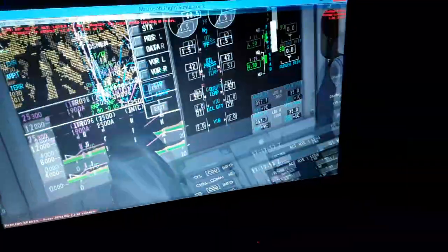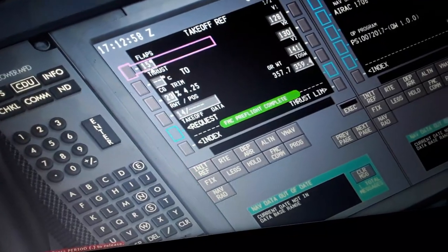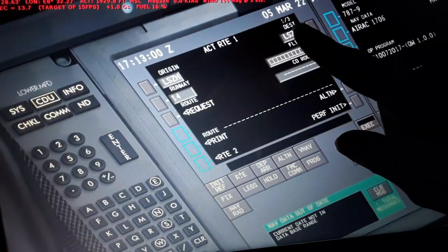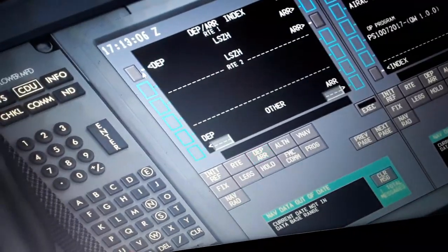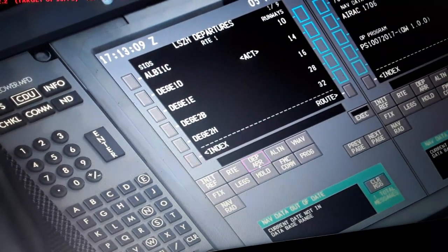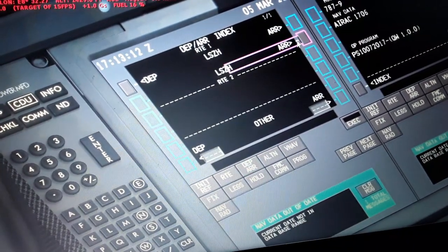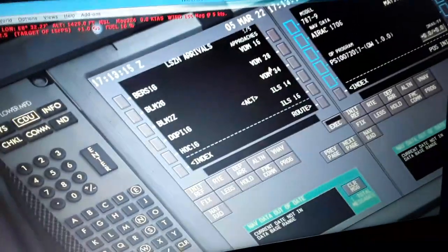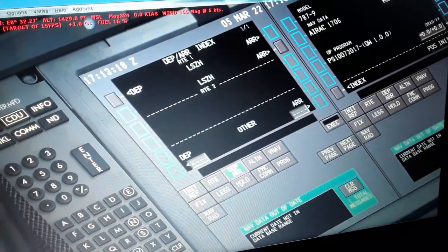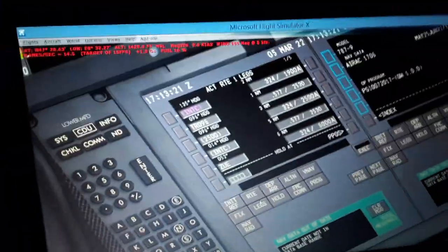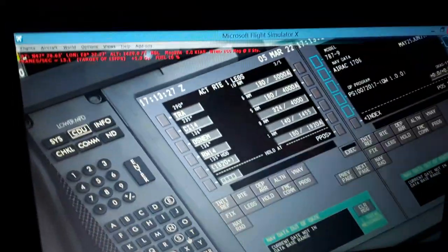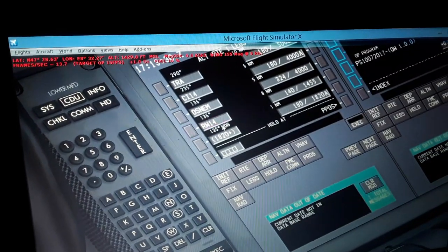We use the flight management computer here for alignment, the GPS position. So I will show you how to use the flight management computer. We have the initialize, route, display, origin, departure, destination, runway, select 14, departures, the SIDs, standard instrument departure, waypoints and fixes, arrival over here, standard terminal arrival, waypoints and fixes, with this ILS localizer runway. So this departure and arrival creates a small flight plan from takeoff. Over here, climb, cruise, then descend, approach and landing to this runway, 14 over here.